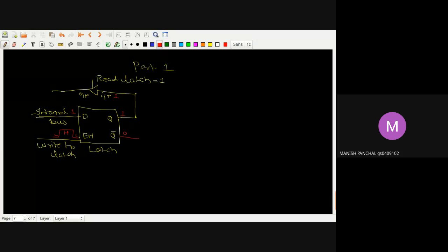Further, this circuit is just like this, that this is connected because you know the port 1. So port 1 will be used for what purpose? Anybody? Port 1 will be used for what purpose? Sir, input output. This is used for input and output. So whenever you are drawing a circuit for any of the ports, please remember that you should know the duty of that port. So for example, port 0 will be used for the IO as well as the time division address and data bus. Whenever talking about port 1, it is plainly used for the IO ports.